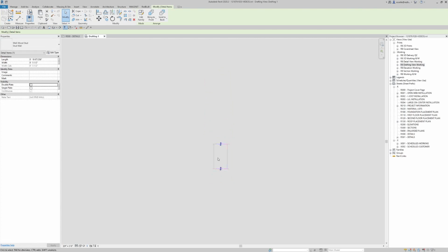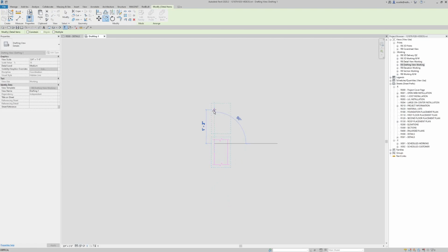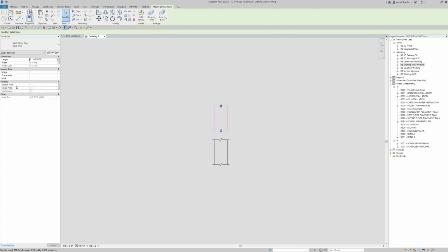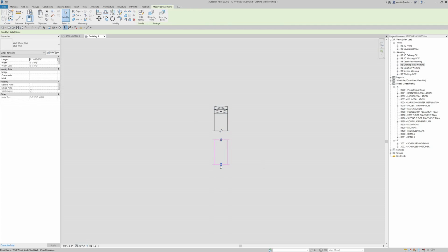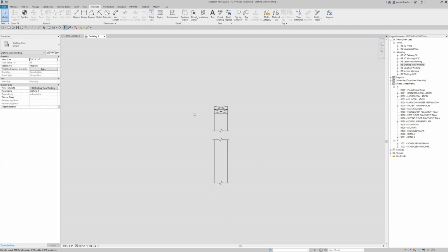This is a great function when you have a parapet or walls below and you want to cut your walls. Now, if you're going to cut the walls and you want another wall, you can simply copy this wall down or up and then go and change our plate to double. Now I have created a break in my wall. I'm going to have joists lower and higher with some ledgers in this example, so we'll leave that.